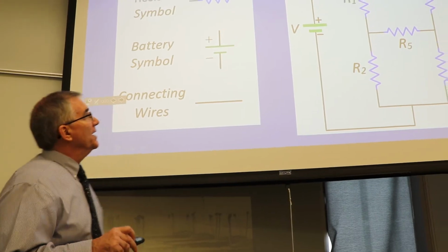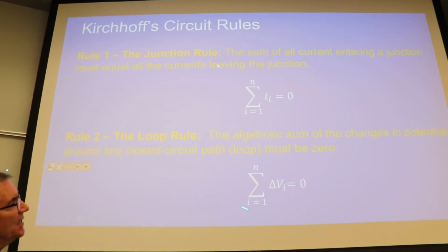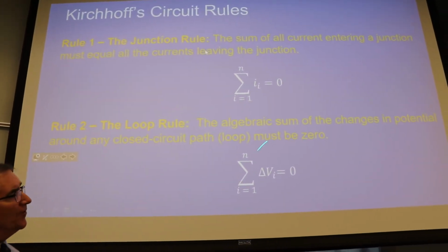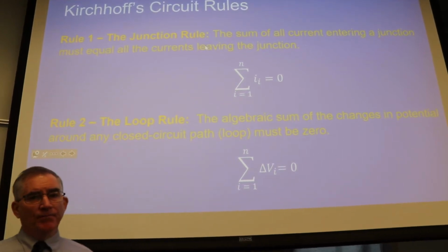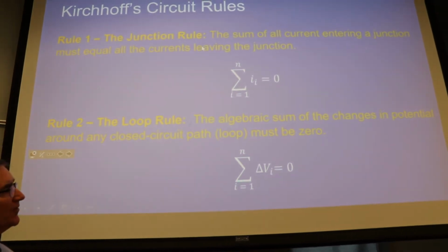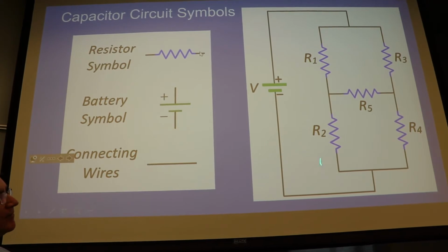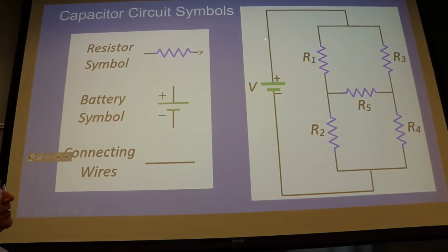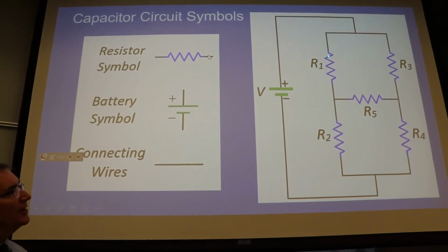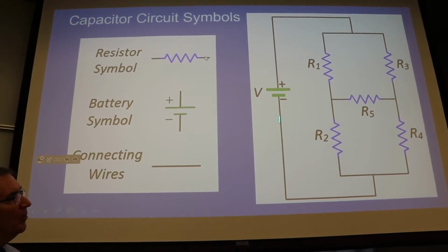All right. Now, the next equation says if you go around a loop, all the voltages have to add up to 0. So if we go back to that picture again, if we pick this loop right here, the electrons come out with all that voltage, and they come down here, and then they drop it, and then they drop it, and then you see you're back home at 0.